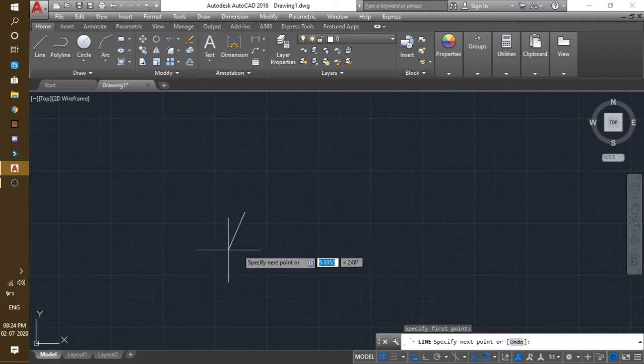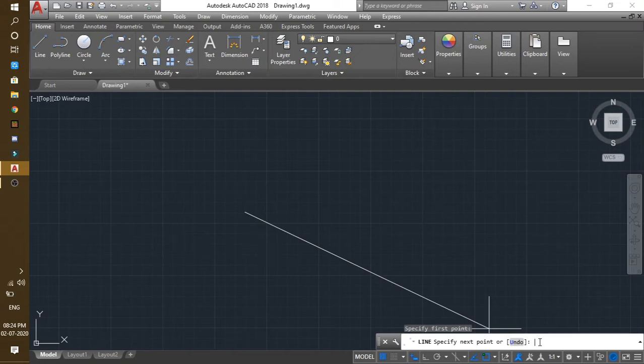Now after your starting point is selected, just go over to this command box and all you have to do is type add. Everything else will almost remain same. You have to put in your coordinates as you did earlier, but the coordinates will change a bit. You'll see it in the next steps, but the first coordinates will remain same. So to start off your rectangle, just type in your first coordinates, that will be 20, 0, because we want 20 length in the x-axis and none elevation. So just type in add 20, 0 and press enter.